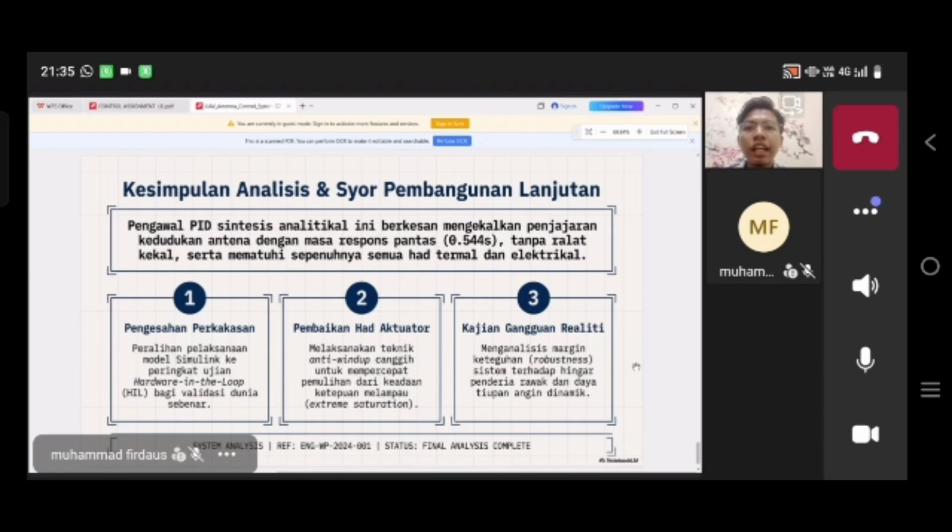To further enhance the performance of the control system in future design, we recommend implementing the synthesized PID controller parameters on a microcontroller unit and testing using HIL simulation or Simulink to evaluate real-world sample rates.